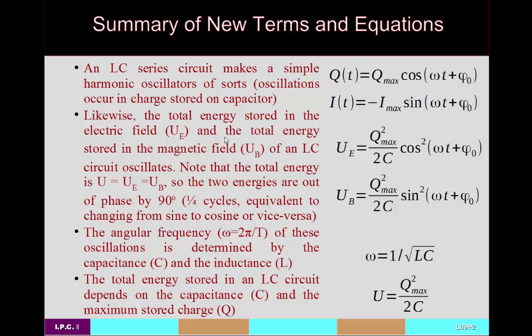If you have an LC circuit instead of an LR circuit, then what you have is the circuit equivalent to a simple harmonic oscillator, where charge takes the place of displacement and current takes the place of velocity. And again, the current is 90 degrees out of phase with the charge. That makes sense because you can treat it as if all the charge is on the capacitor itself, and that's all the charge that can make up the current. So when there's zero charge on the capacitor, all the charge is in motion, and therefore you have a maximum current. And when all the charge is on the capacitor, there is zero current left in the circuit to move, and hence you have zero current.